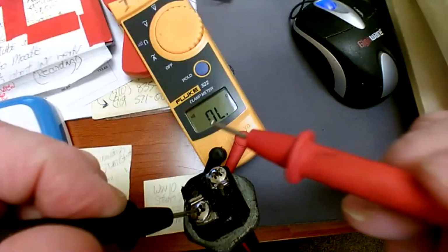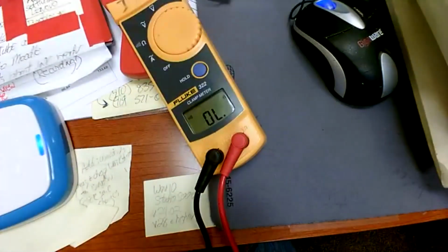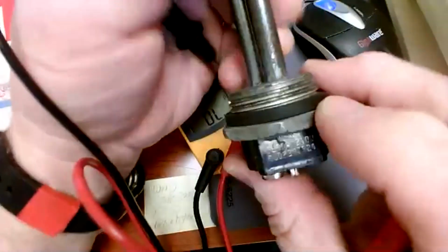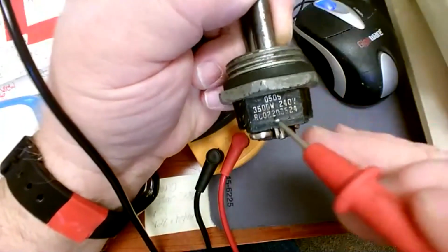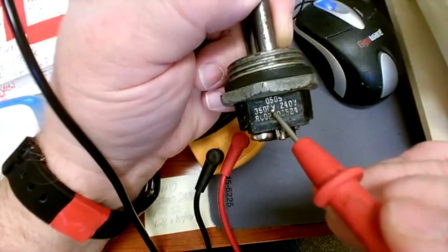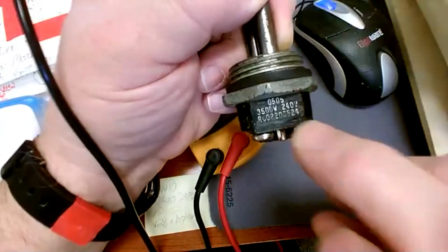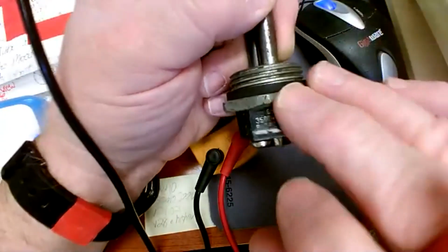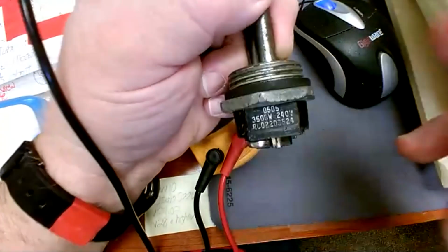This heater element, your calculation that you did, using that data right there directly on the heater element, it allowed you to actually calculate a resistance that's consistent even when it's cold or hot. So heater elements can be calculated directly right off of that as far as how many ohms they should read.